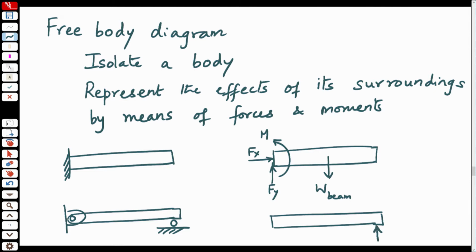So, that means, let us call this point A, there is a force in the y direction which is being applied by the support to prevent the movement. And then if you look at the pin joint, the pin essentially prevents x and y motion, but it will allow rotation. So, it does not provide a resisting moment.